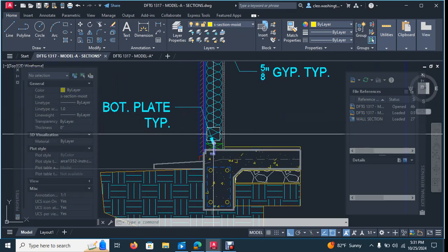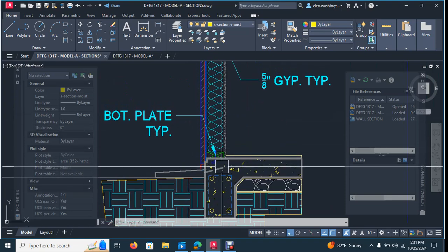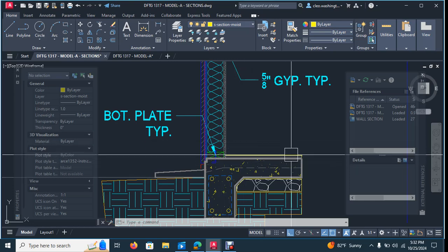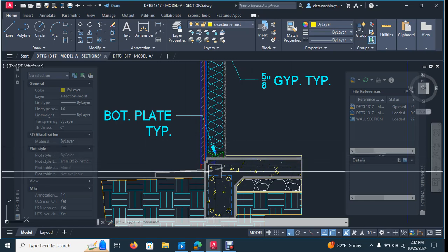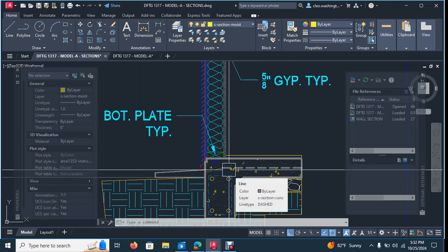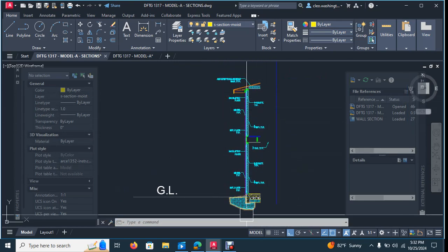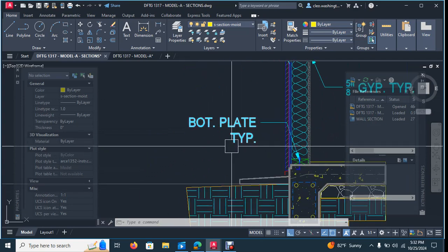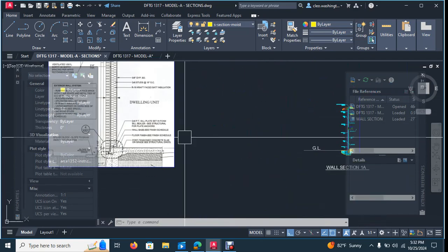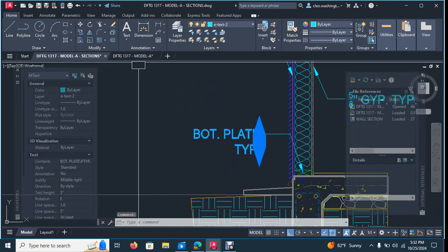But always remember, all right, when you apply the brick, you never move the walls in. You always move everything out, and then you adjust the slab out to house the brick or to house whatever material that you're putting on it, okay? So I'm not gonna put the notes in, and you may have to change the size because these notes are a little bit more extensive. So we may have to change the size. Let's see what size do I want to use.